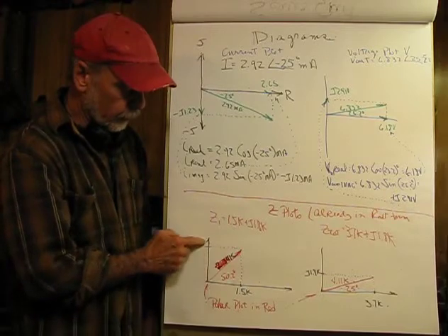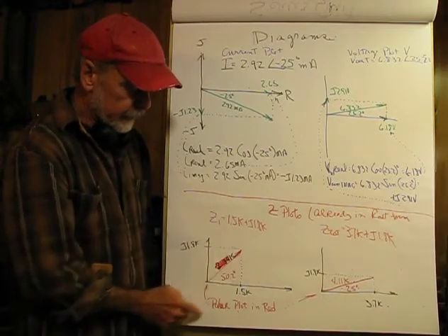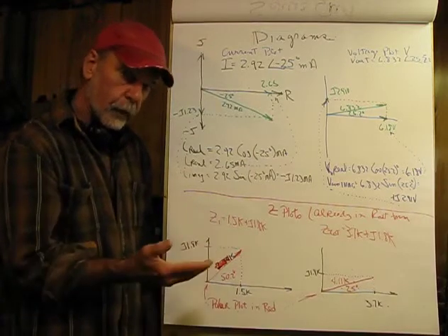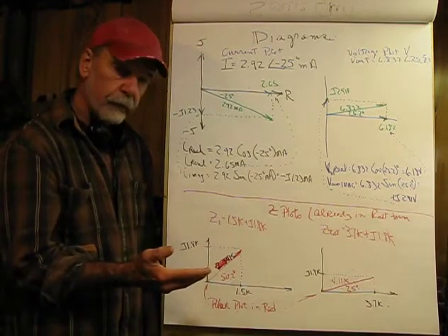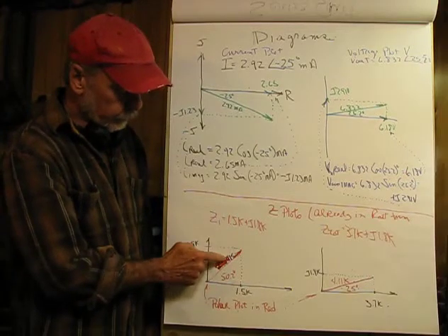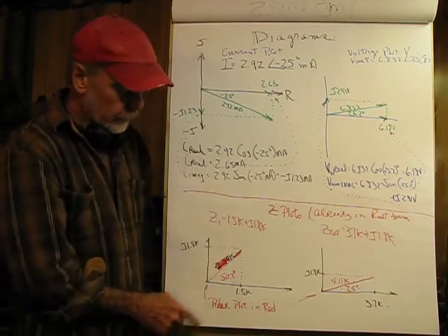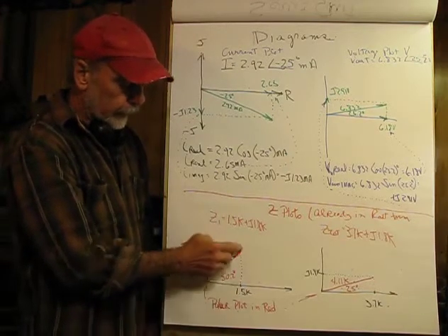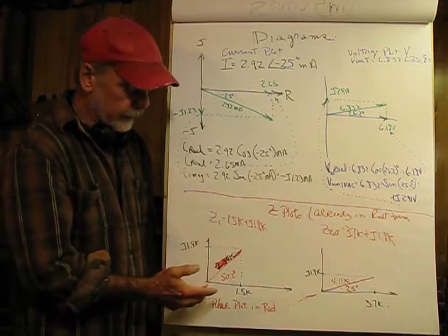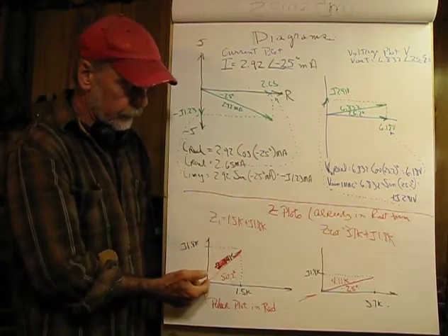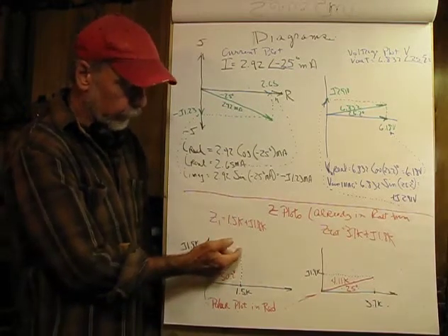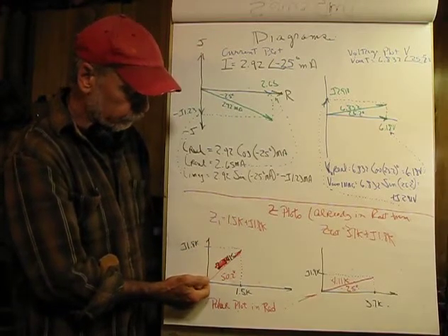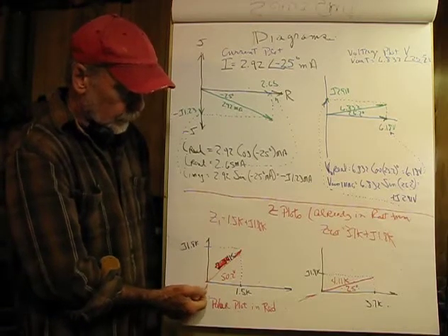Connect the dots again, and then I get the sum total that we calculated in polar form before, so we could do the division easier, and that's 2.34 kilohms, and the angle that we had before was 50.2 degrees. So I plotted this in rectangular form, which we were given, didn't have to figure that out, and then just filled in the length of the impedance of Z1. So that's what that would look like.